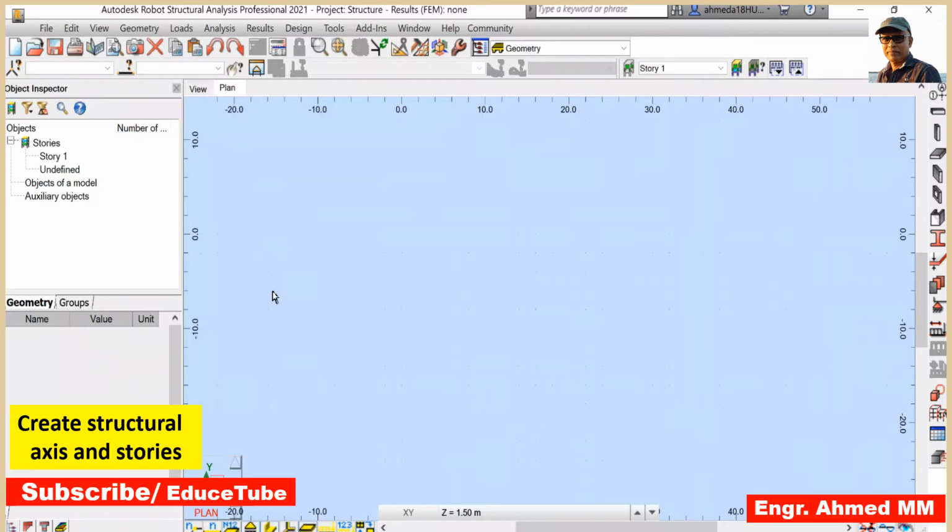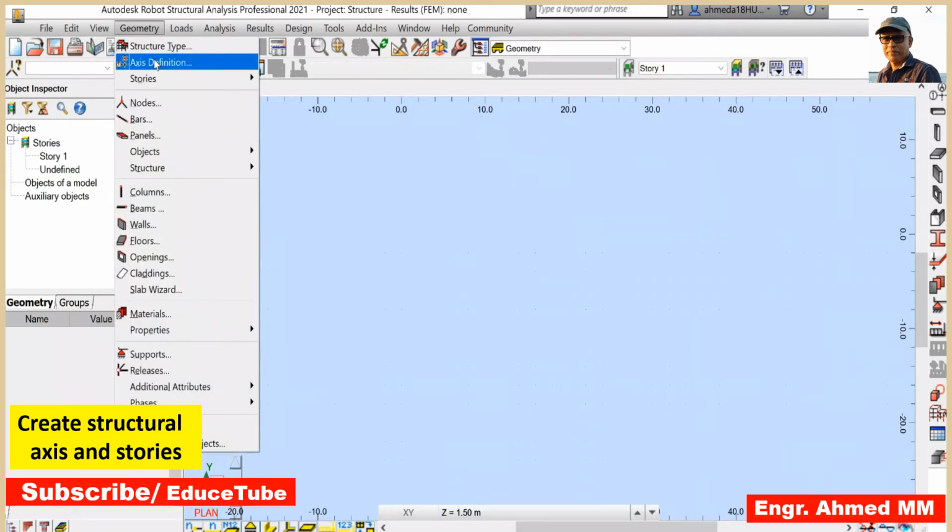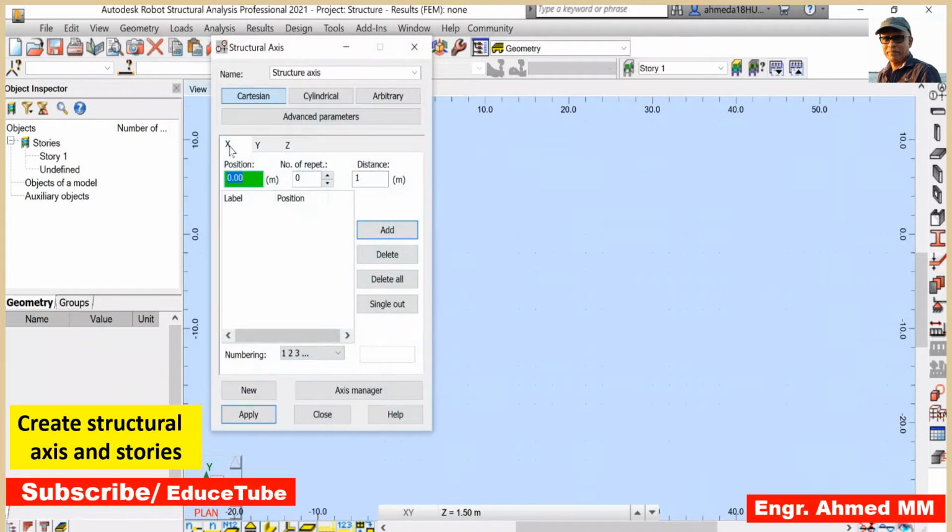From the menu bar, our task is to click geometry, choose axis definition. On the X tab, keeping position 0, number of repetitions say 7, and distance 7 meter.